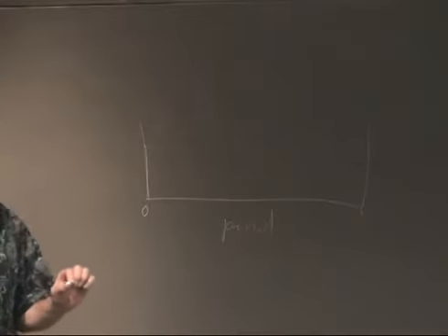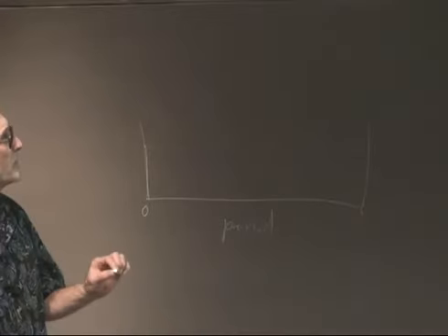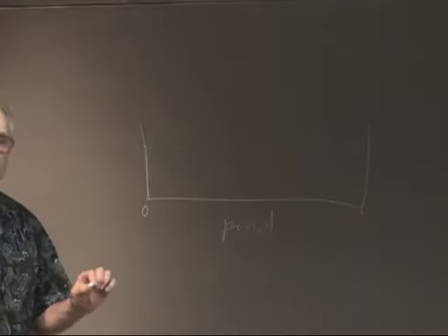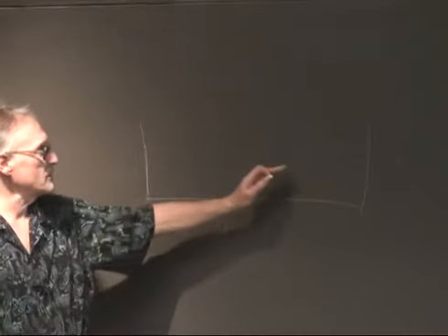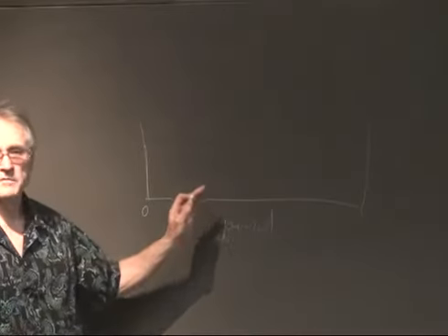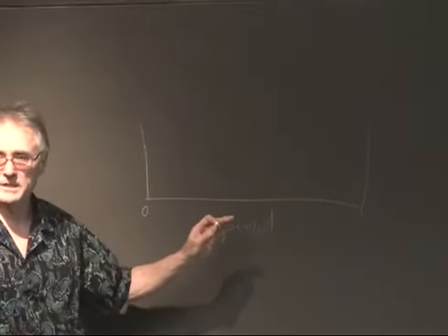If you use the other mode, the continuous pulse mode, then you get some very odd results at the boundary conditions of 0% and 100%. Basically, it generates a 50% duty cycle square wave at half the frequency, which you do not want.